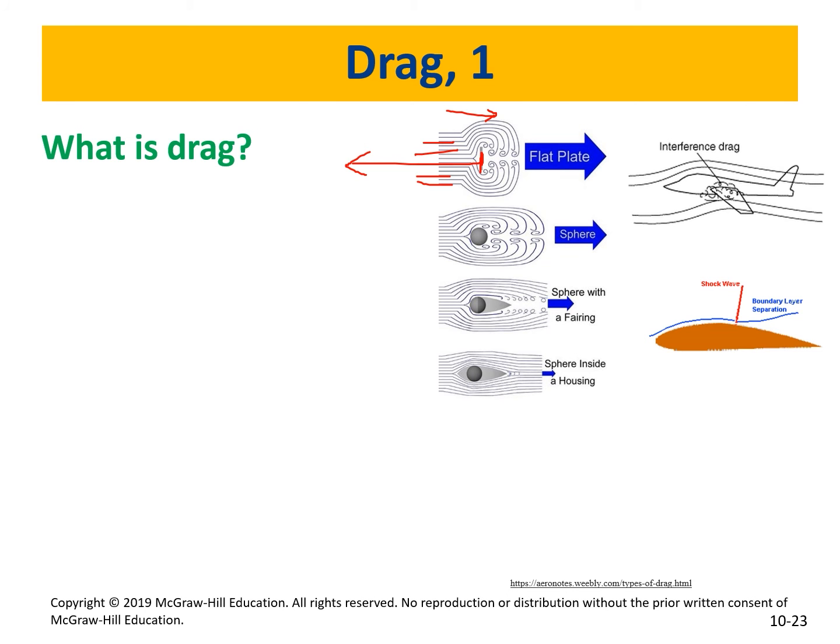If it's a sphere, you have a smaller drag force. If it's a sphere with a tail at the end, that will be a smaller drag force. And if you have an indentation at the beginning and the back, you have even less drag. Now, if you look at the airplane, the wings, we don't have cylindrical, rectangular wings, because that is going to create a huge amount of turbulence. That's why we try to have some sort of curvature at the beginning and a tail at the end, to reduce the drag as much as possible, to control it, not just reduce it. Does that make sense?